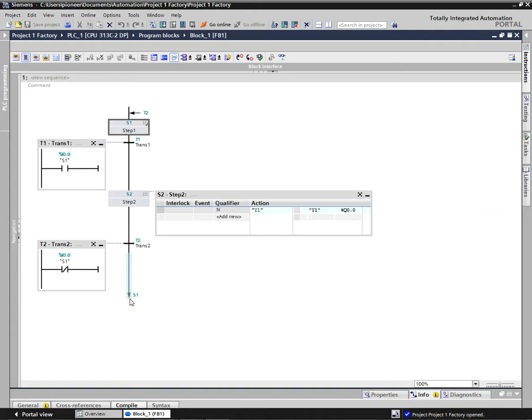It means going to S1, working as I0.0, S1 not working as I0.0, and this is the Q, Y1 working as Q0.0, and this is a momentary command.